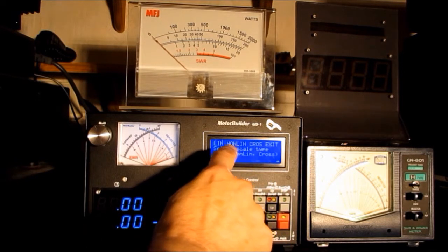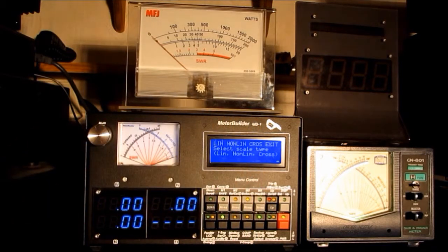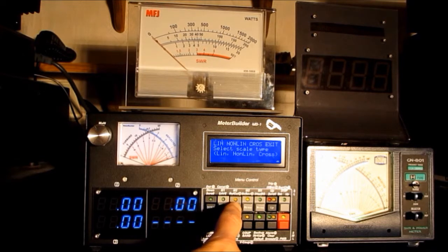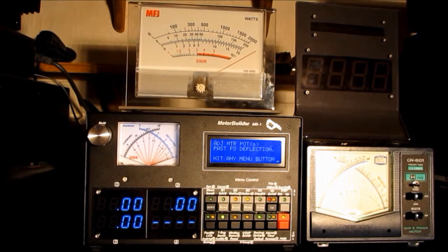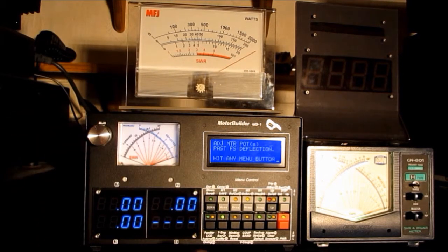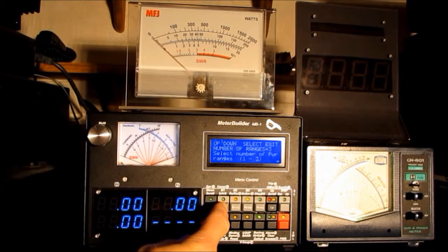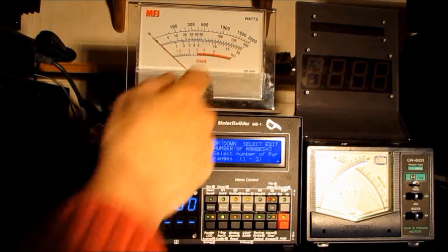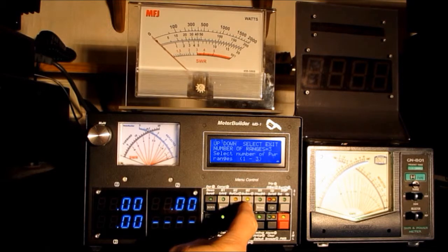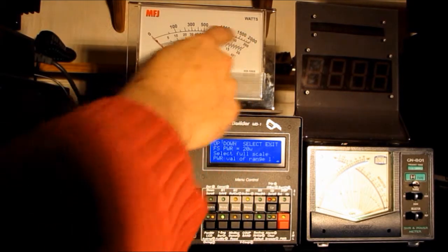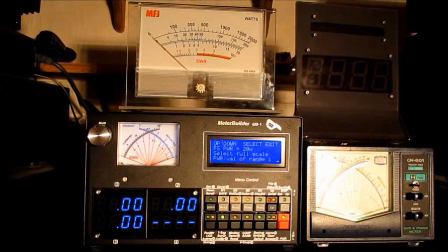I'm going to pick the nonlinear choice. Linear is your standard linear scale meter. Cross-needle meter we've already discussed. So the second menu button is the one I want to choose. You can see the needle is already adjusted to go beyond full scale. It's going to now prompt me similar to what it did in the cross-needle meter. I'm going to select 3 ranges. I'm going to use 20, 200, and 2000. Full scale power of 20. Had this been 3,000 watts or 5,000 watts, I would be using 30 or 50 at this point.